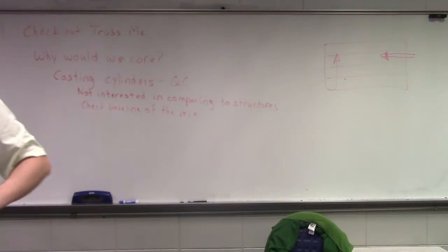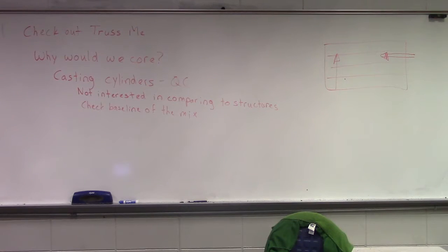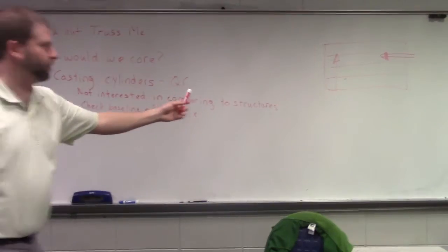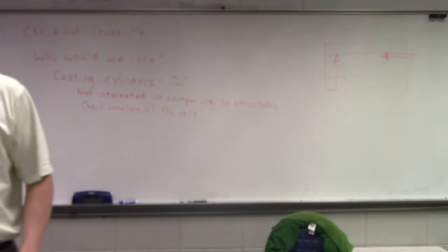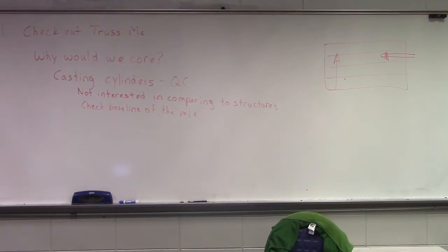So can you just fill your core back up with more concrete? Yeah, or you could do a patch mix, or yep. But you have to keep in mind these were just blocks that they had on site. They weren't using them for anything. When you're talking typically about coring, you're talking about taking something out of the project. Yep. So it's typically just some sort of patch that gets put in. If you go out and core a roadway, usually it's just the asphalt patch that goes back into it. But yeah, you can put in a high strength, high early grout into place, so it'll have a higher strength component and it'll cure really fast. Okay.